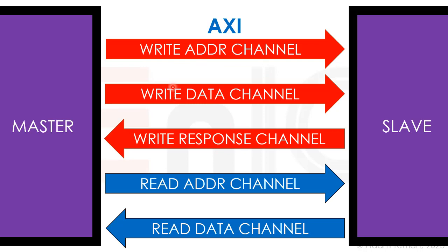And that means we can have different transactions going on completely simultaneously without bothering the other ones. And there's no guaranteed ordering. So the CPU can send several writes and several reads, and it doesn't have to wait for the responses. It can even have different sequences between the write address and when the write data is put on, because each of these different transactions is going to have an identifier. And the slave over here is going to be that DDR controller that's going to get all of these things, buffer them up and decide at which order to actually send them over to the DDR. And then when it gets the answer from the DDR, it's going to be able to send back the answer through the read data channel or through the write response saying it was done.